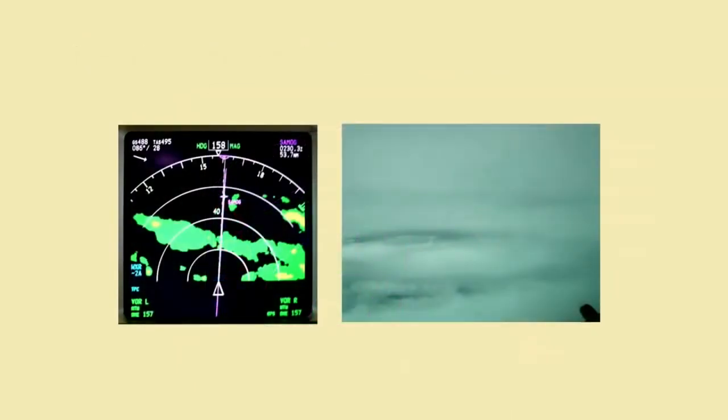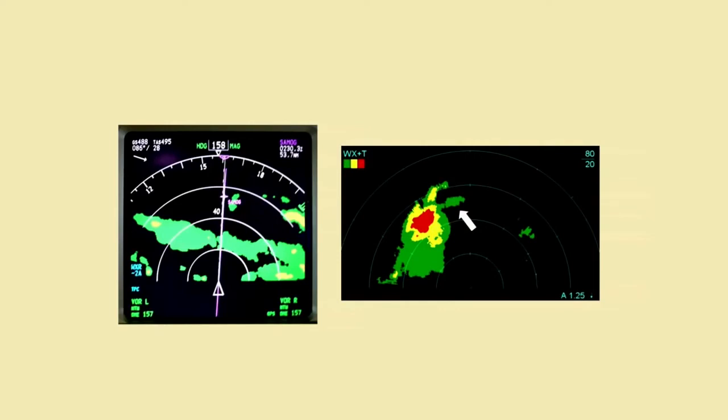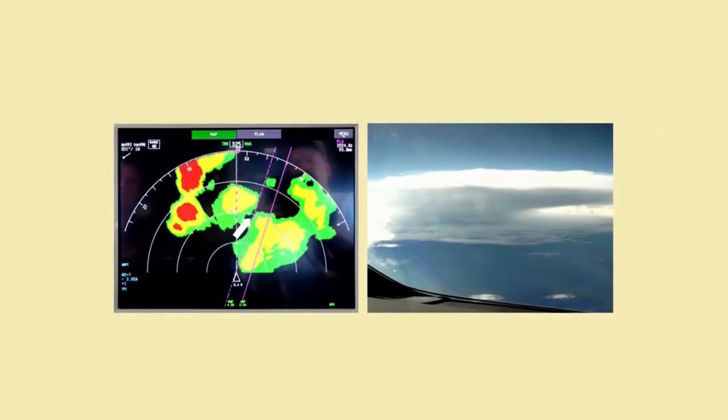As can be seen by this view out the captain's window, the radar is displaying weather at 25 nautical miles. In this case, green represents a pressure ridge, and the flight crew can anticipate light to moderate chop when the aircraft transits the region. However, the two fingers that extend to the right of this storm core indicate an internal shear force. Even though these returns are green, they still represent a threat to the aircraft. In fact, this dark area between the two fingers is an indication of a hail shaft and should not be transited.